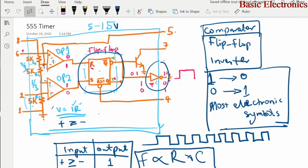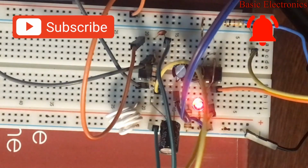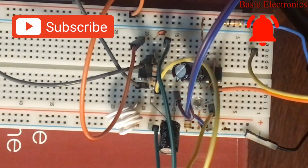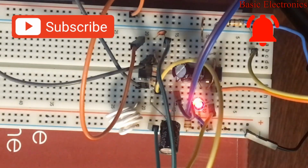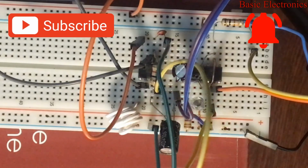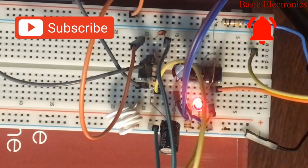Okay. Alright, let's go quickly and look at another circuit that we built around this 555 timer LED blinker and what else we can do with it. On the left hand side you have the low frequency Astable Multivibrator. On the right hand side you have the audio frequency Astable Multivibrator. Now we have a speaker we're going to connect to the audio frequency Astable Multivibrator.